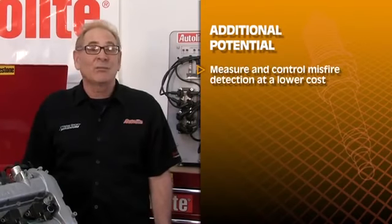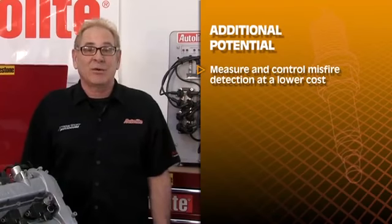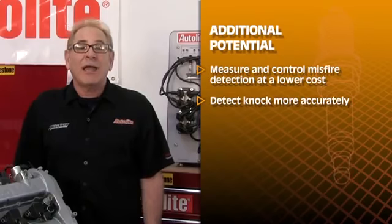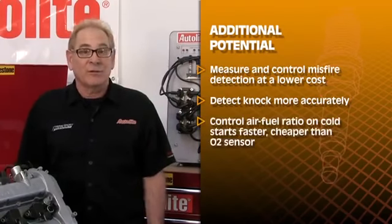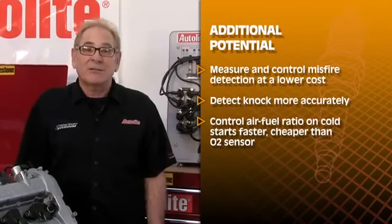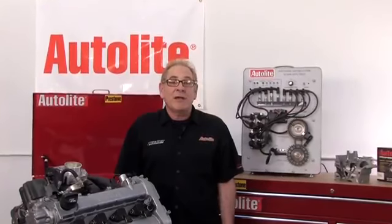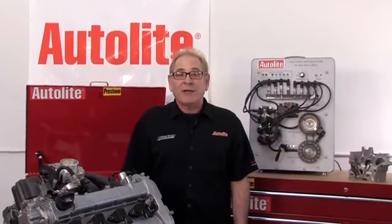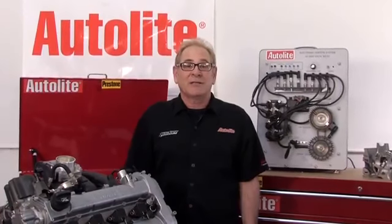Ion sensing can be a lower cost way to measure and control misfire detection, which is usually done today with a cam and crank sensor correlation. It can also be used to detect knock more accurately than current knock sensors, and it can control air-fuel ratio on cold starts faster than an O2 sensor and at a lower cost. There are many other applications for this type of technology. Most are aimed at more accurate engine controls, as well as the cost savings over multiple electrical sensors.